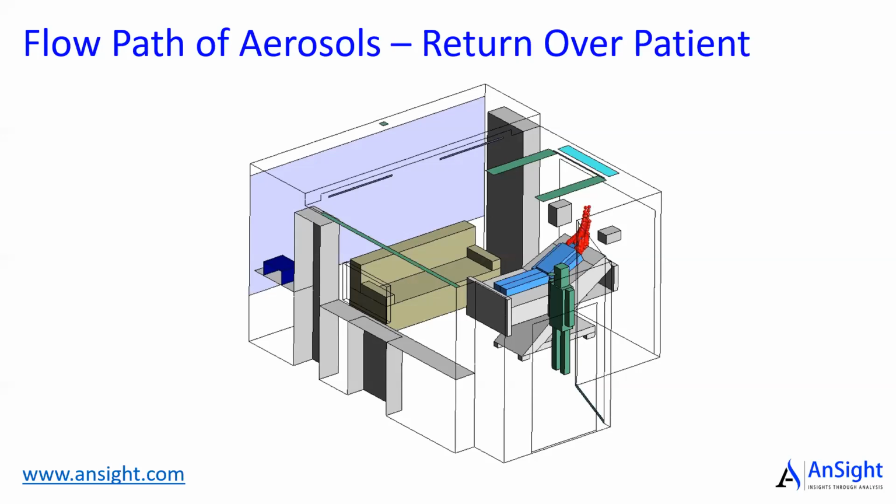You may ask, will it work exactly like that in a real room? Probably not. But if you compare between the two designs, this design shows a lot of promise. And therefore, if I have to design the patient room, I will design it like this, because it is providing the path of least resistance without hurting the other aspects of the ventilation, the thermal comfort of the occupants, and so forth. Okay, so I'm not going to get into the details of the thermal comfort part because that's not the emphasis of today's talk here.